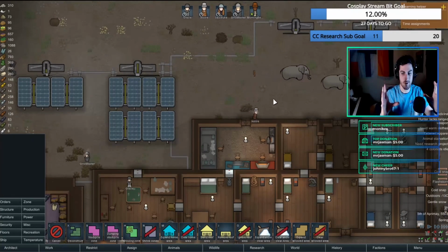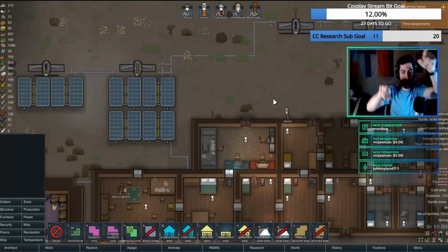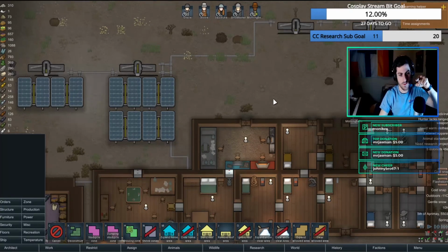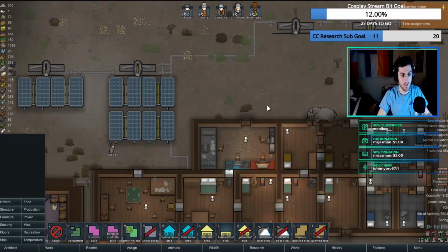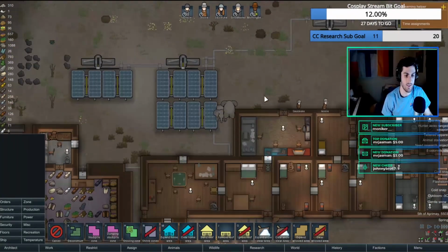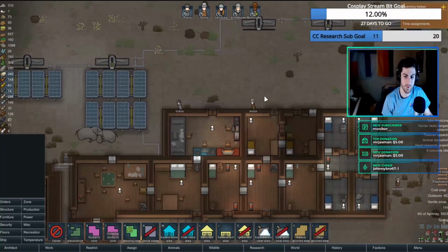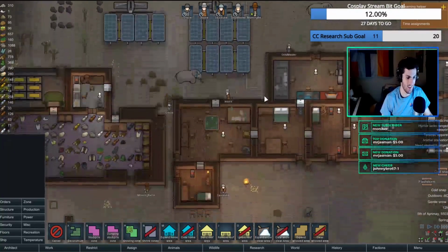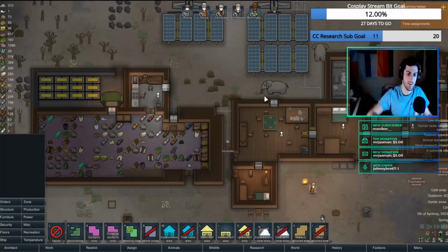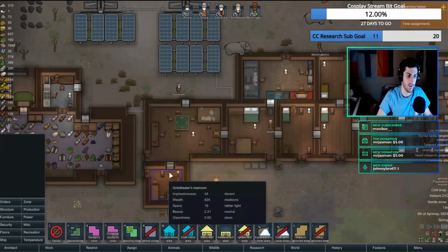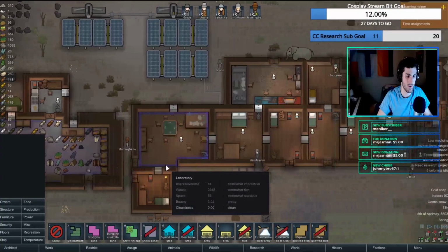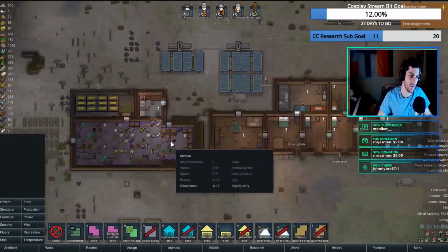And that velocity profile is only in one cross section, but it rotates around. So the velocity in the middle is the maximum velocity that you get. And if you have a steady state incompressible fluid, which means the density can't change, then your velocity will be constant in the z direction, the direction of the flow, I guess. Look at that, you guys are helping me study for my quiz on Monday.